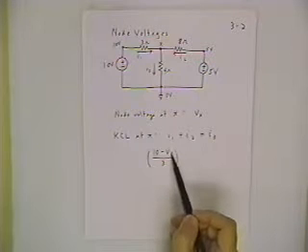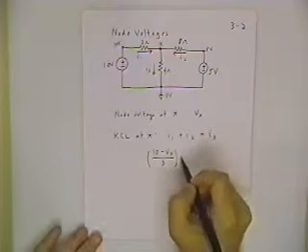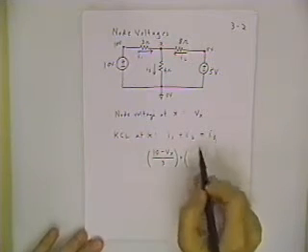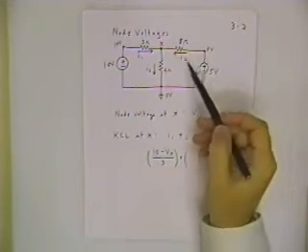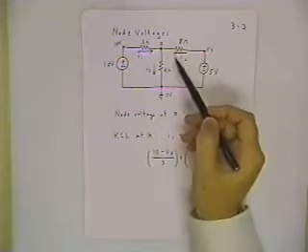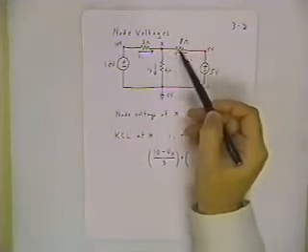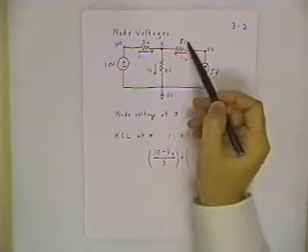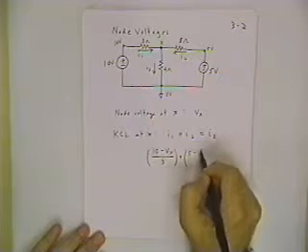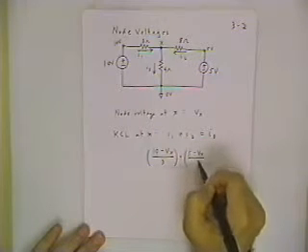It happens to involve an unknown quantity, but as soon as we finish writing the equation, we can solve for that unknown. What you would write for I2, the current I2 going from higher to lower potential in this left-hand direction, from 5 volts to V sub X volts through an 8 ohm resistor, is 5 minus V sub X divided by 8.